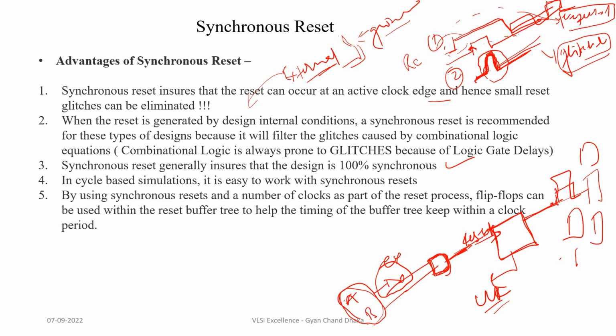If it is getting difficult to close the timing of the reset tree, we can pipeline it and introduce some flip-flops which will make sure that the timing can be closed within a clock period. So this is another advantage of synchronous reset.